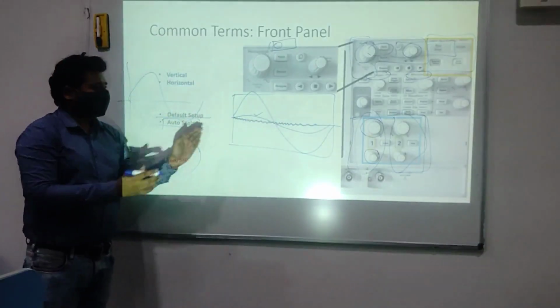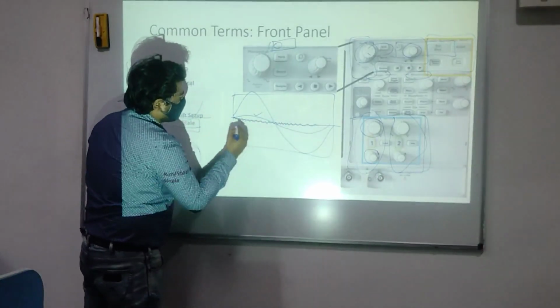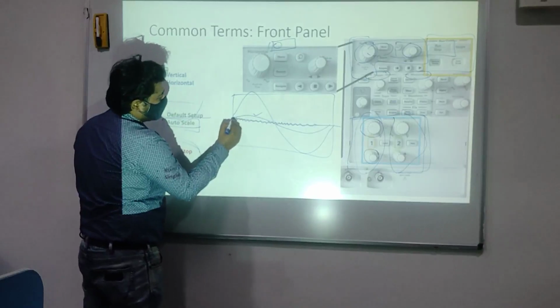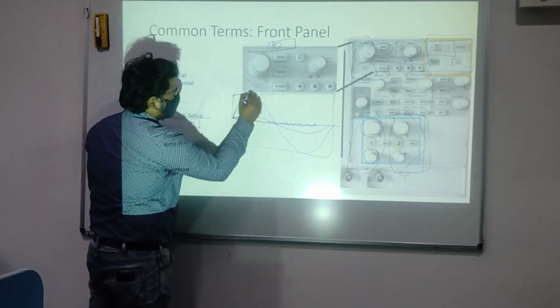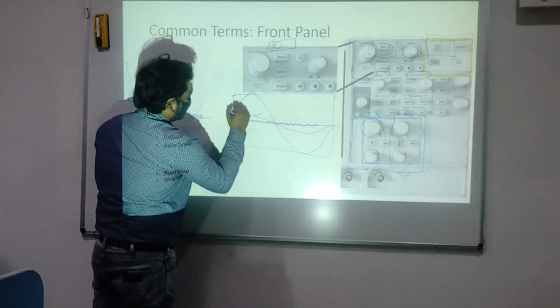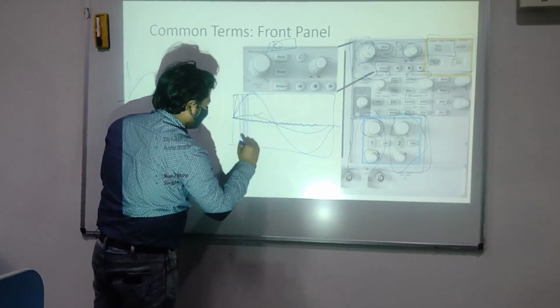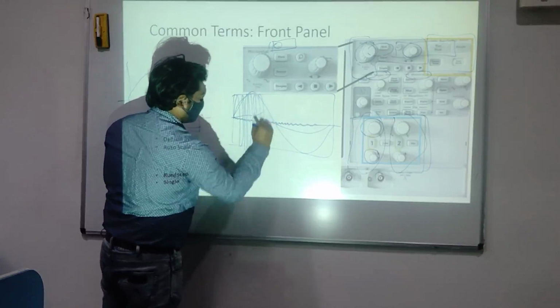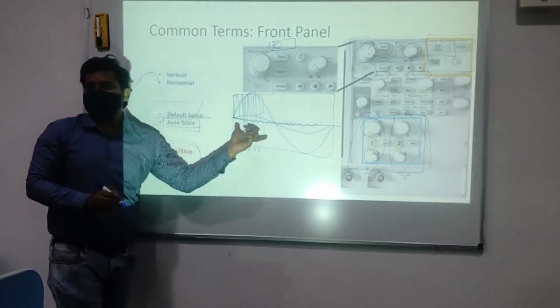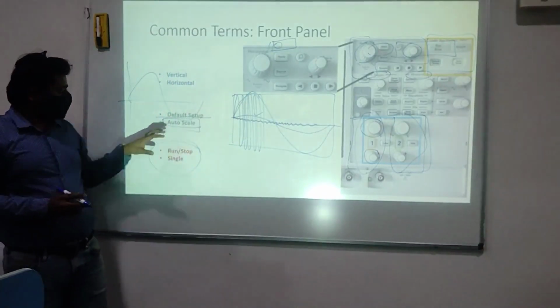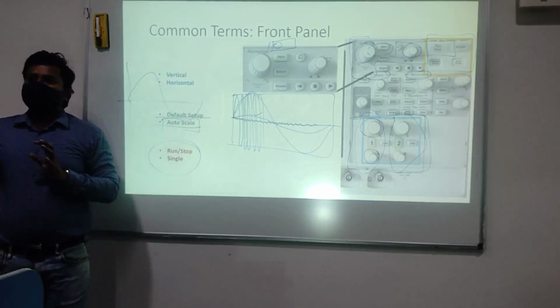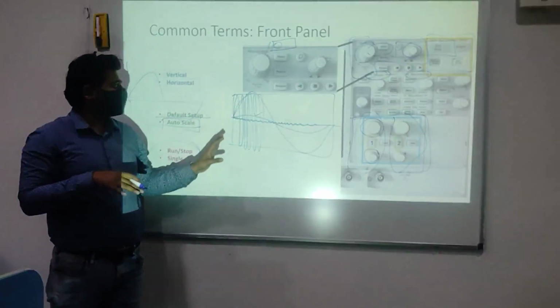Okay, and so on. So this is not separated apart. For example, you have done the correct voltage setting and it is like this, but it might not necessarily be plotting like this and will be plotting like this. Okay, so then you need to adjust the time division setting. So this auto scale, by sensing the signal, can do this.